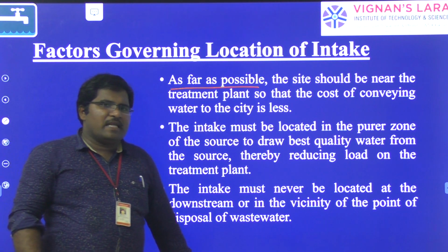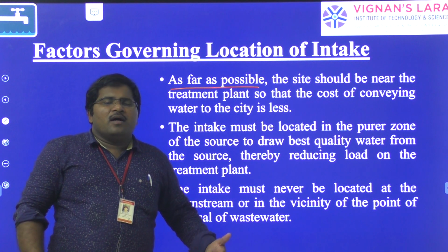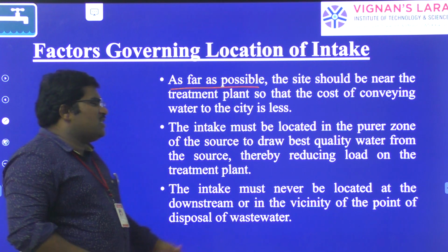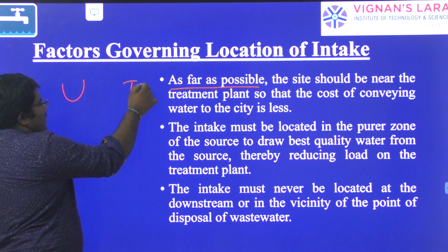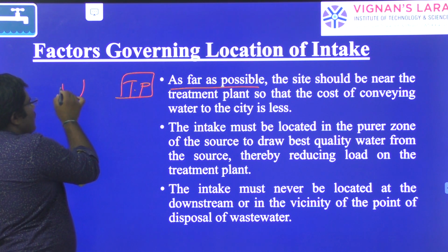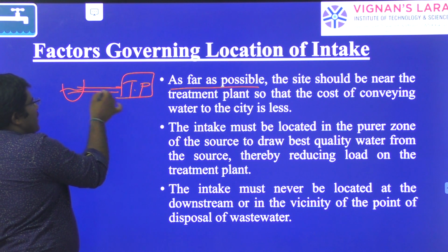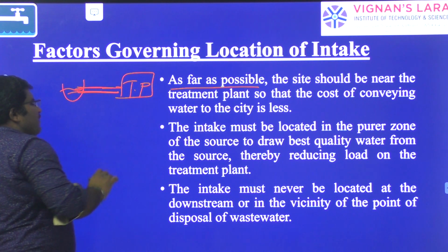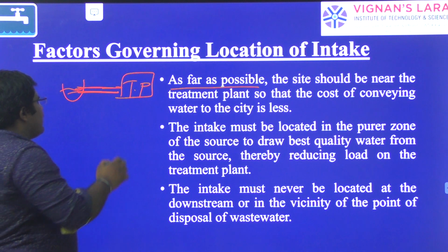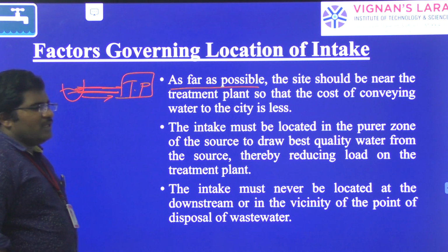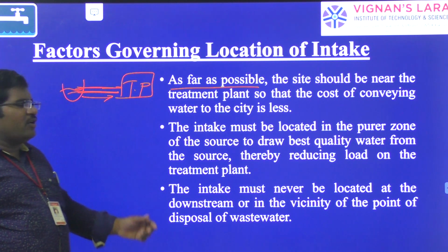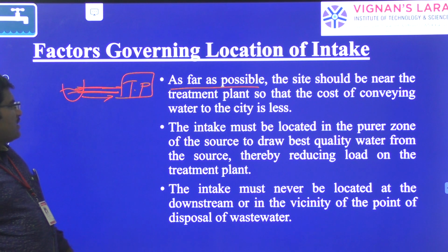So you have to select a place with a short distance between the source and the treatment plant, because the cost of pumping the water from the source to the treatment plant reduces when the distance is small.